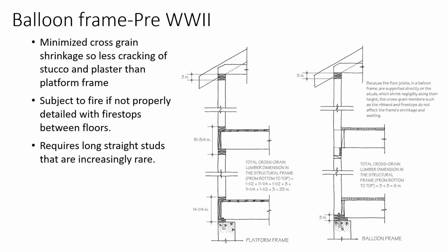The hot air rises and it will instantly go up, and then your whole house burns, your first and second floor. So the problem, apart from the fire stopping, was it required very skilled carpenters to do it, because you had to notch in all these, like this rib end that's holding up the joist had to be notched in. And I'll show you this in an isometric on the next page.